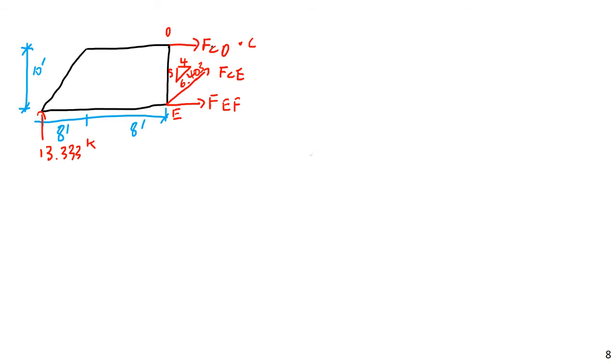Or if I was interested in this force, I'd probably want to sum moments about point E, because neither this force nor this force will generate a moment about E. Again, that will produce a result fairly quickly. Oh, and I'd probably also want to mention the dimension from here to here is also going to be 8 feet, because that's going to be important.